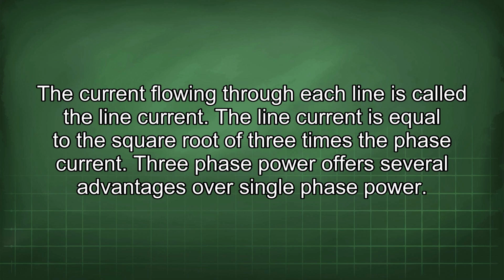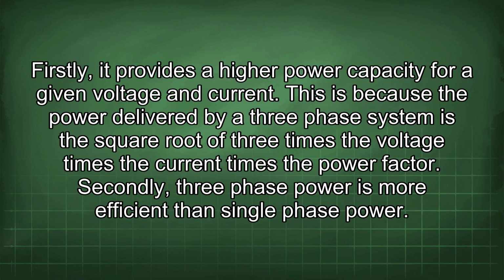Three-phase power offers several advantages over single-phase power. Firstly, it provides a higher power capacity for a given voltage and current. This is because the power delivered by a three-phase system is the square root of 3 times the voltage times the current times the power factor. Secondly, three-phase power is more efficient than single-phase power.